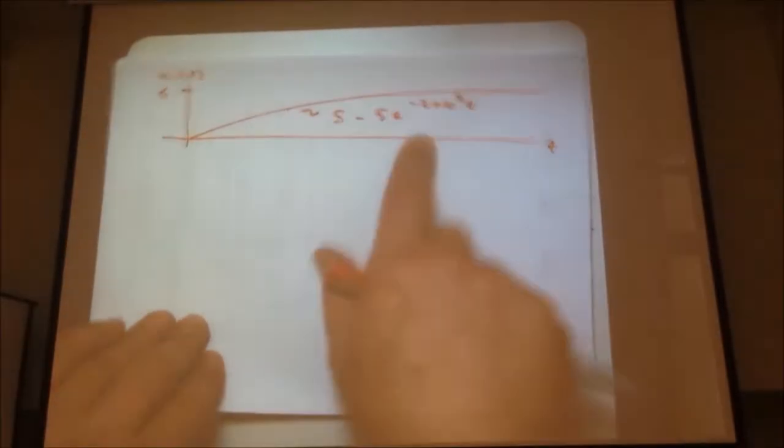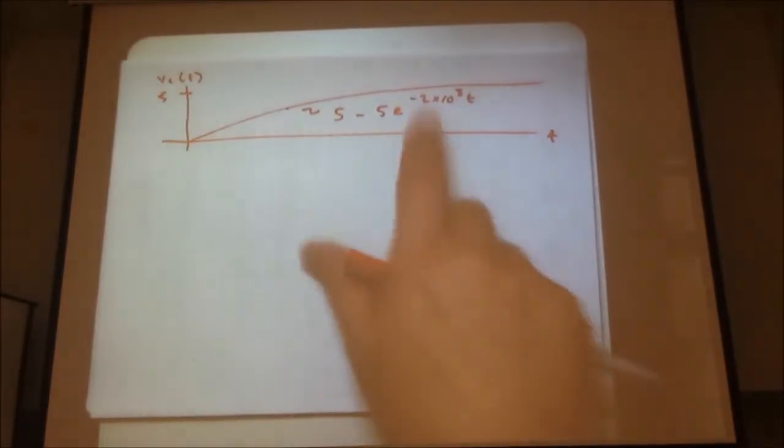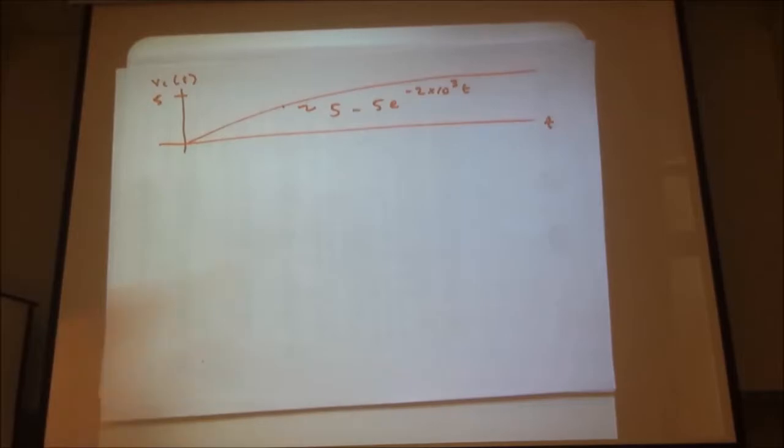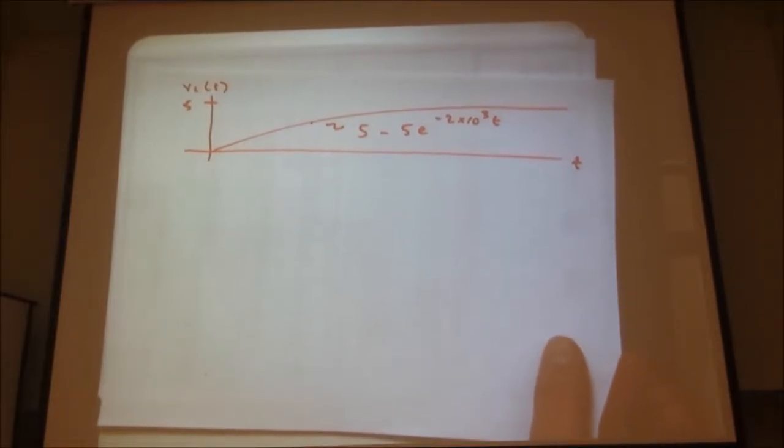Things to think about. Strongly overdamped, low response, only one of our S's, only one of our roots matters really, the dominant root, so to speak. And we'll see a comparable situation, though not quite the same, when we look at underdamped. Everybody okay with this? Questions?